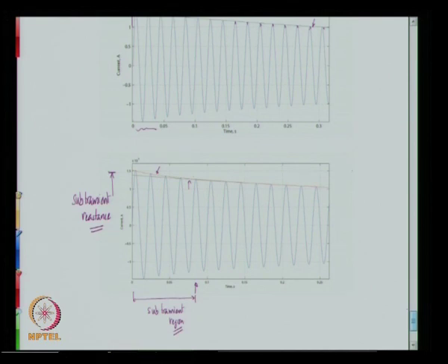these further terms like xd dash, xd double dash, xq double dash, t dash do, t double dash do, and so on. All these, t dash d and t double dash d, are useful in defining the behavior of alternators when subjected to sudden disturbances. We have looked at a specific example where the alternator is subjected to a very severe disturbance, that is a full short circuit at the terminals of the machine.